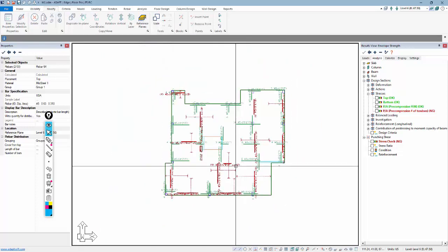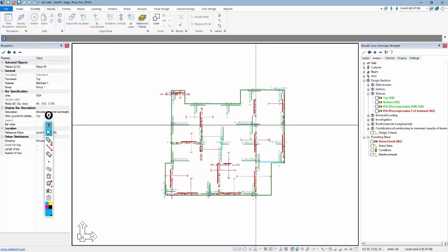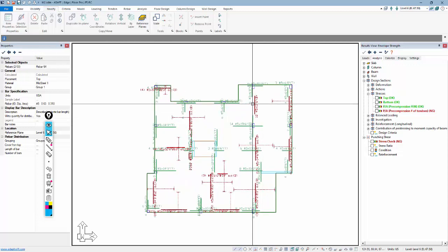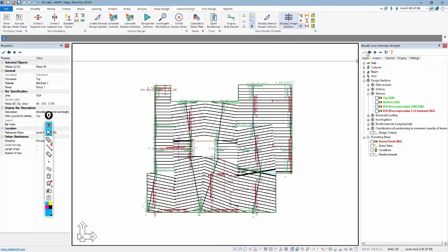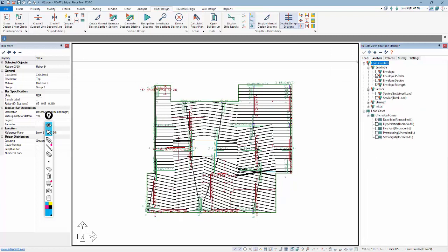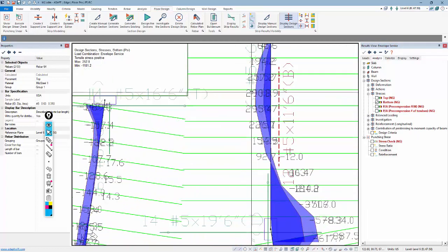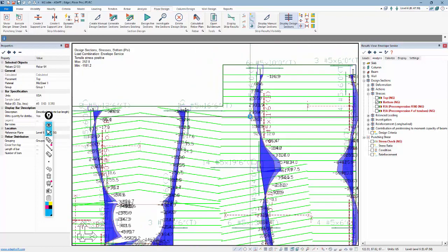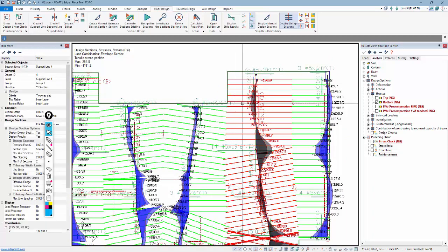Okay, so this is the output for the minimum requirements for that slab, and all of these bars correlate back to a design strip. They're all based on a strip. For example, this 12 number 5s here at the bottom, if we go back and look at the Y direction strips and I look at the stress for, let's say, envelope of service, the bottom stress, the maximum is around 295. So anything over 2 square root of f'c requires reinforcement. That's where that reinforcement comes from. It's based on this stress that's essentially calculated based off the integrated moment and the precompression in that one section.